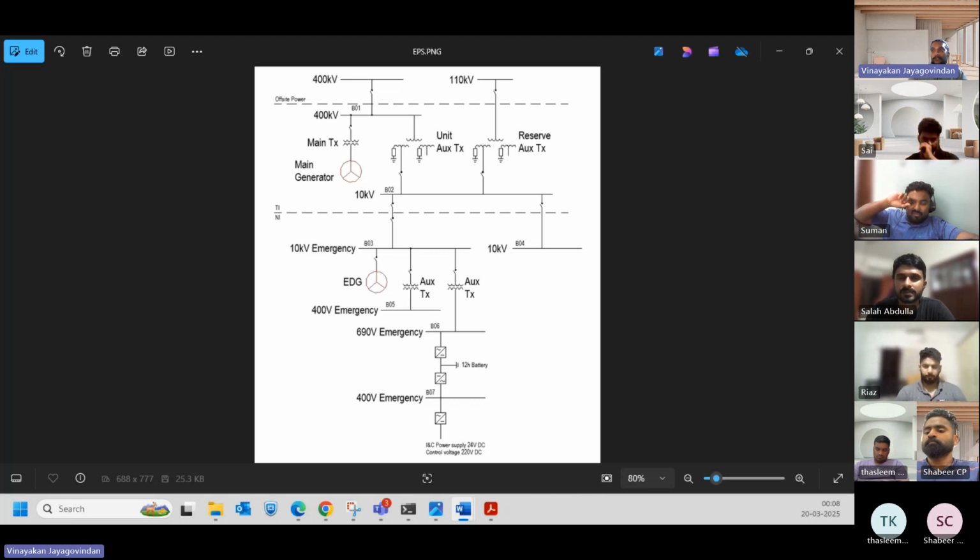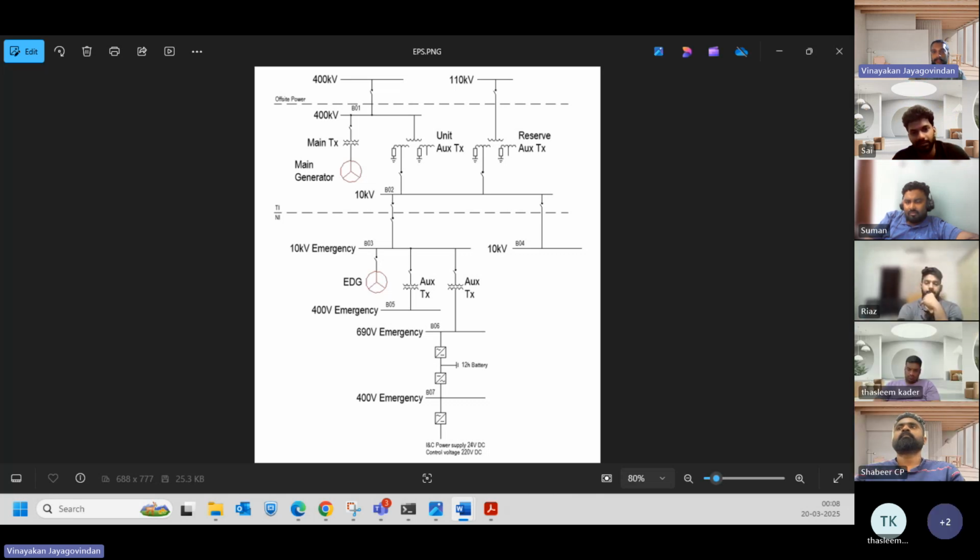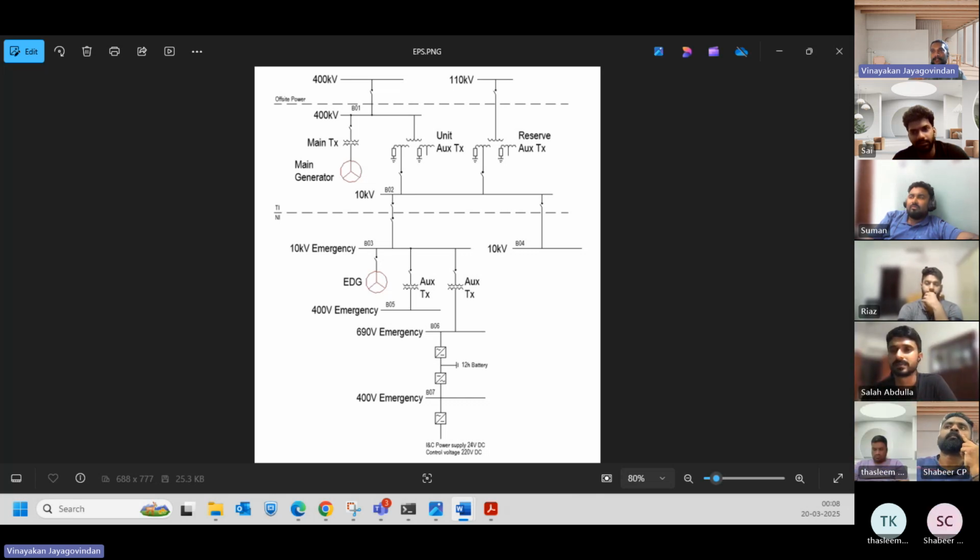The diesel generator load sequence outlines a step-by-step process of reconnecting the electrical loads. The electrical loads such as the main heat sink injection pump, which we use for removal of decay heat, and the low head safety injection pump. And similarly, the chemical volume control system charging pump, emergency feed water pump, component cooling water system pump, essential service water system pump, and emergency boron injection system pump, to the EDG.